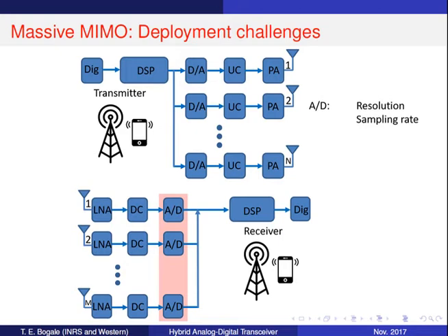In fact, as the number of antennas is larger, the received signal will likely experience a smaller SINR at the input of each ADC unit in a realistic massive MIMO setup. This is because a massive MIMO system likely operates in a multi-user or multi-stream communication where the number of antennas is much larger than the number of user terminals or streams, which are usually fixed due to the constraints in the channel coherence time.